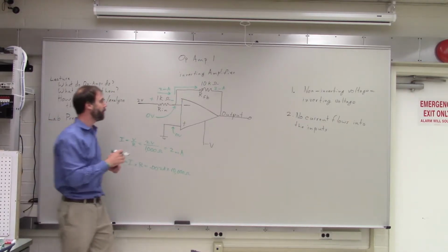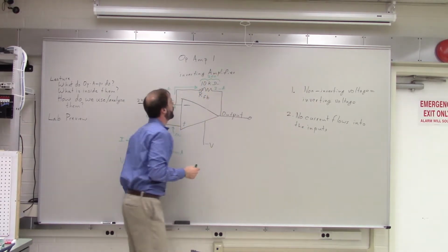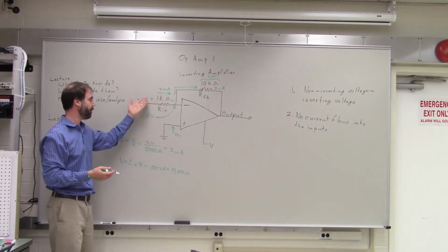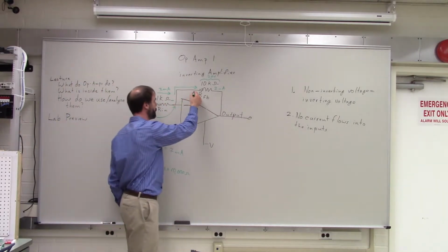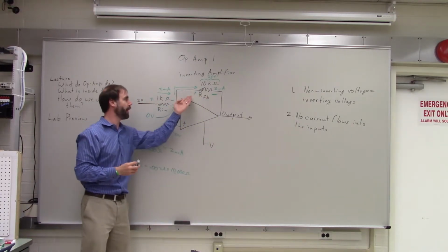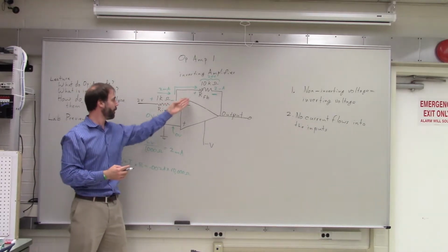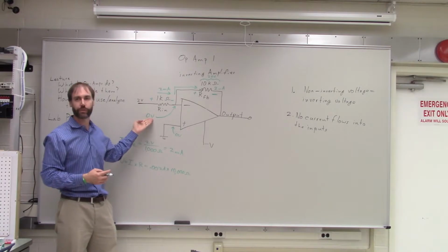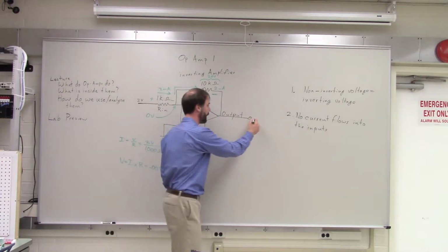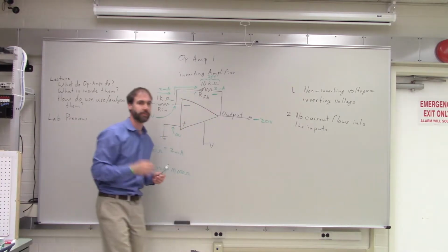Good question. So it's a difference of 20 volts, and it's flowing from left to right. The way that I'm drawing it, the current always flows from positive to negative. So that means that the left-hand side has to be positive, and the right-hand side is 20 volts more negative than the left-hand side. Okay? Now we know that the left-hand side is at 0 volts, and then we go down by 20, so our output voltage has to be minus 20 volts.